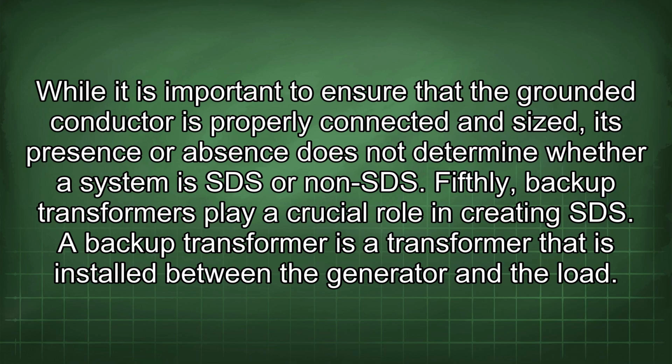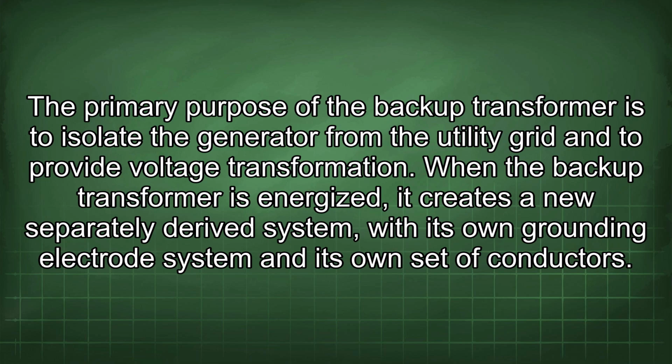Fifthly, backup transformers play a crucial role in creating SDS. A backup transformer is a transformer that is installed between the generator and the load. The primary purpose of the backup transformer is to isolate the generator from the utility grid and to provide voltage transformation. When the backup transformer is energized, it creates a new separately derived system with its own grounding electrode system and its own set of conductors.